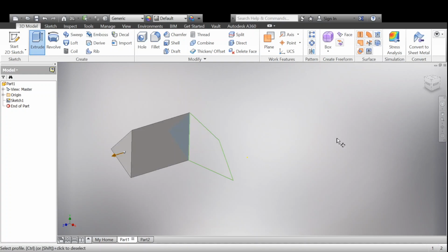And when I do that, I want to show you a couple options. First, this will extrude what's called the shell, not a solid. So if I click on this option here, take a look at what the color changes to. And this is just showing you a shell of that image. So if you were to try to 3D print something like this, it would automatically print it empty. You don't want to do that.